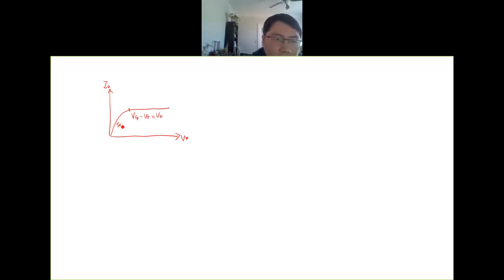And this is the triode. And this is the saturation region. This is at the given Vg. If we consider the channel length modulation effect, then this will no longer saturate. So if you consider the channel length modulation effect,